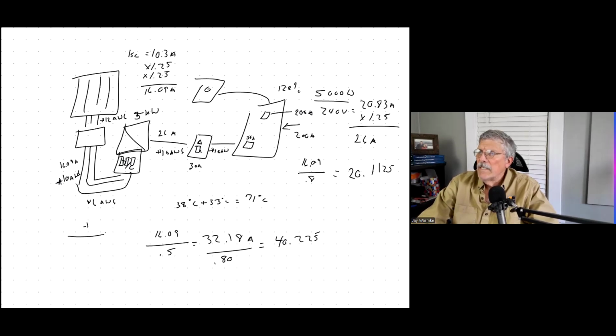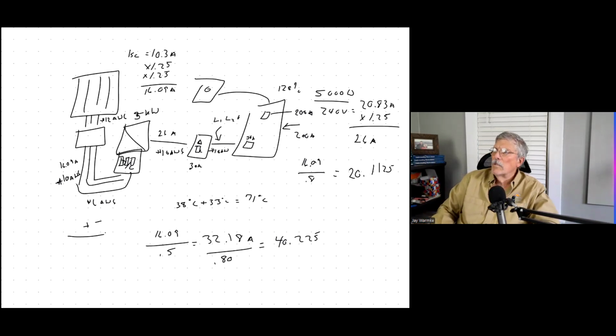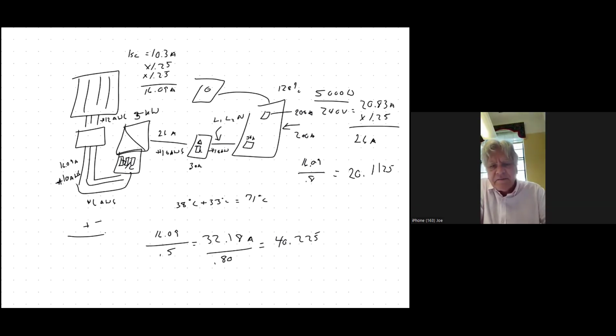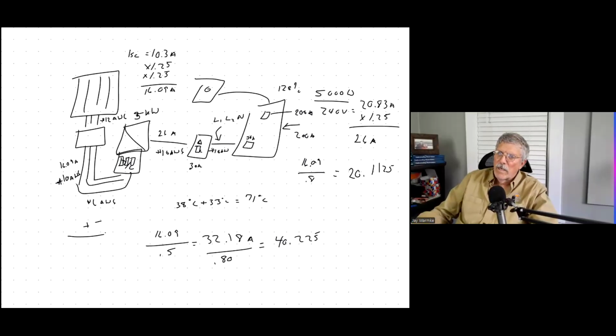But over here in AC, there's probably going to be three wires, because there's line one, line two, and neutral. So that one line indicates three wires. Okay, gotcha. And the ground is also typically in there, but that's a non-current carrying wire, so we can ignore that as far as capacity, because it's never supposed to carry any power unless there's a problem.